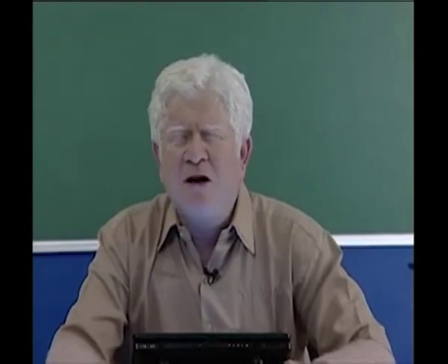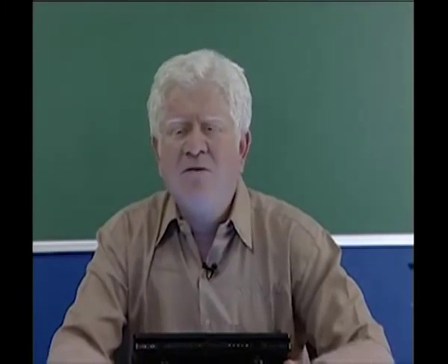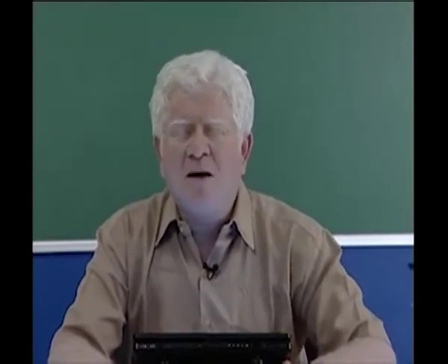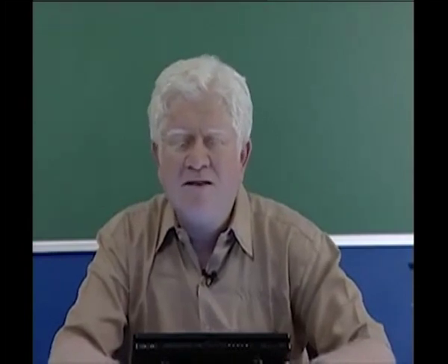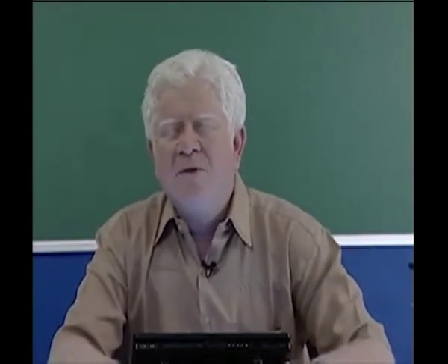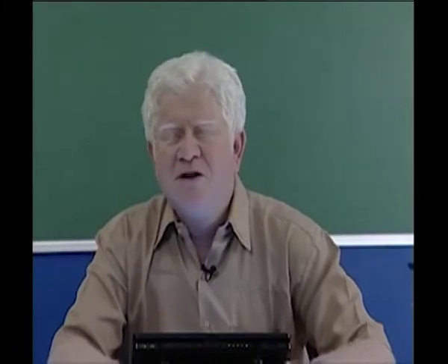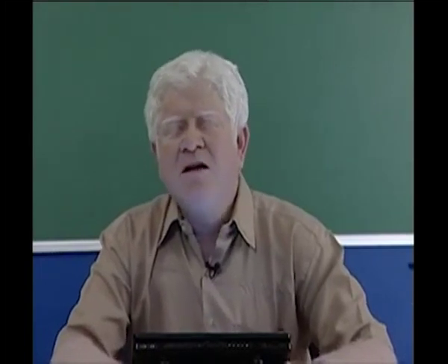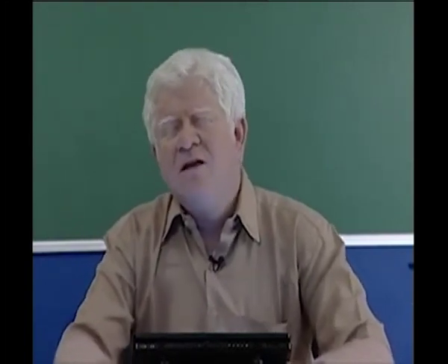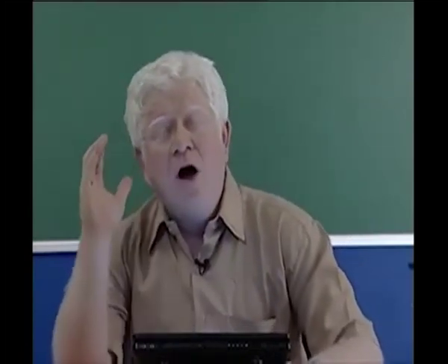For the continuous time case, however, there is a practical problem that arises, and that practical problem is simply that whenever you differentiate a continuous time signal which is corrupted even slightly by noise, then the noise tends to get amplified under differentiation. So, repeated differentiation of a signal can be suicidal. It increases the noise level in the signal to greater and greater extents and reduces the performance of the entire differential equation solving system. The solution to that is to see if instead of differentiating we can carry out a series of integrations.